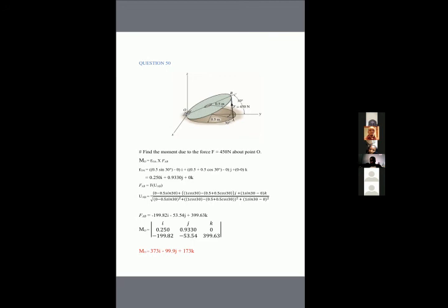plus the 0.5 sine 30 is the one that's shown in this diagram. There's that part which is in green, then the other one is in brown there. So the bottom part there, which is in brown, that's where the 0.5 is coming from. Sine the angle there, which is 30 at the bottom there. So that cosine 30 gets us the y coordinate of point A. So you get the difference, you have your y component of the vector A, B.